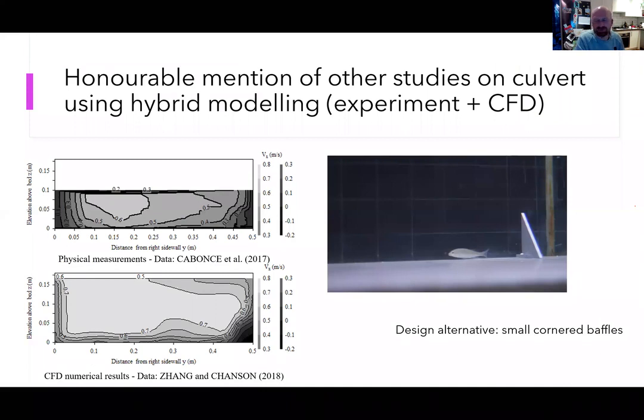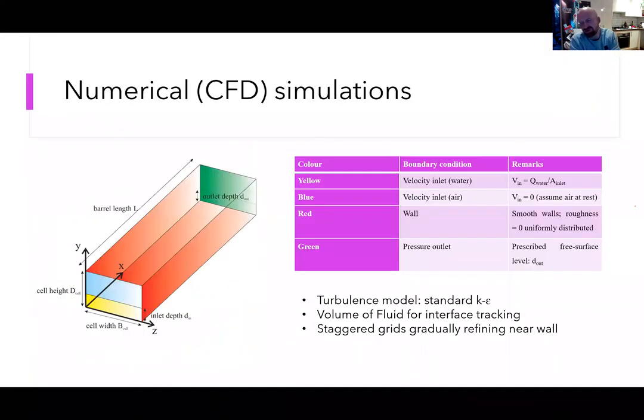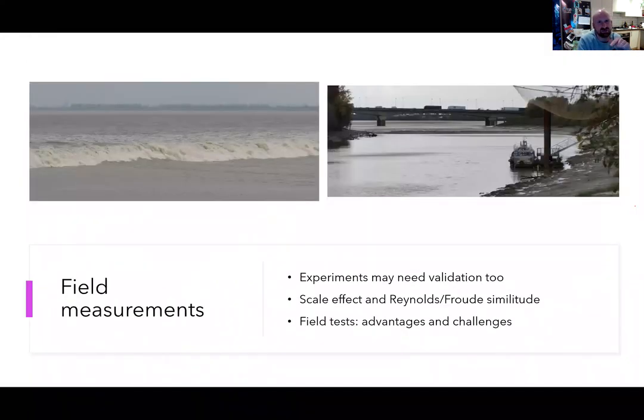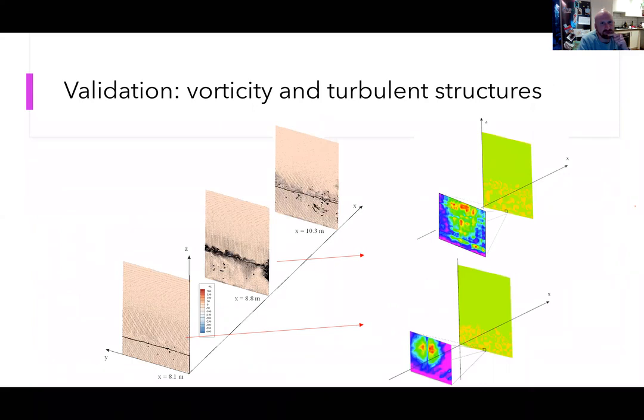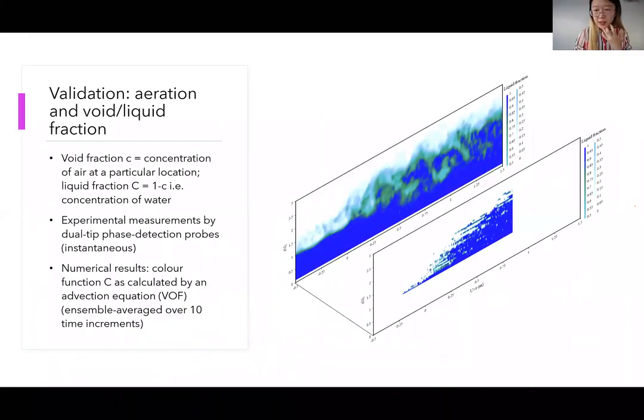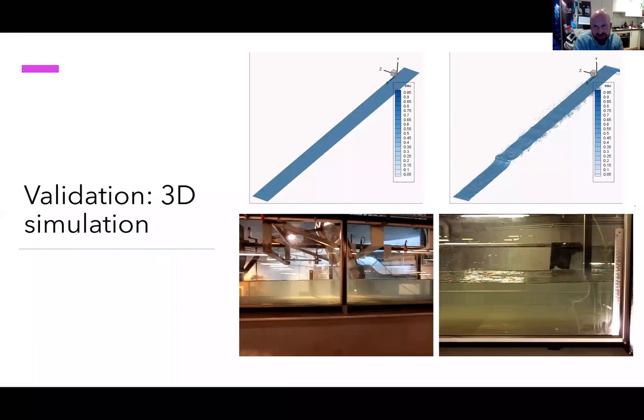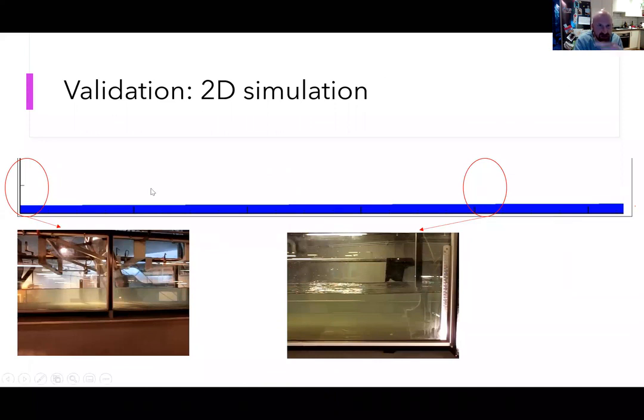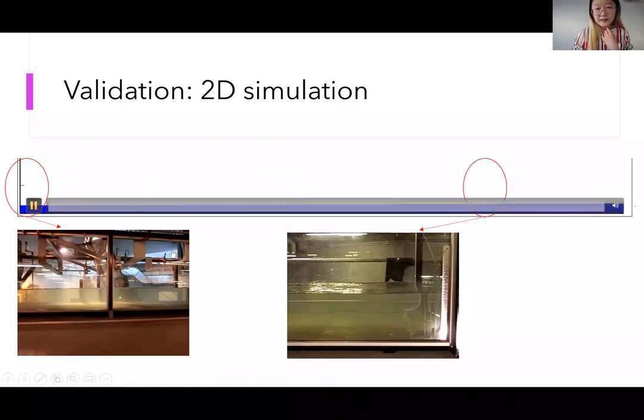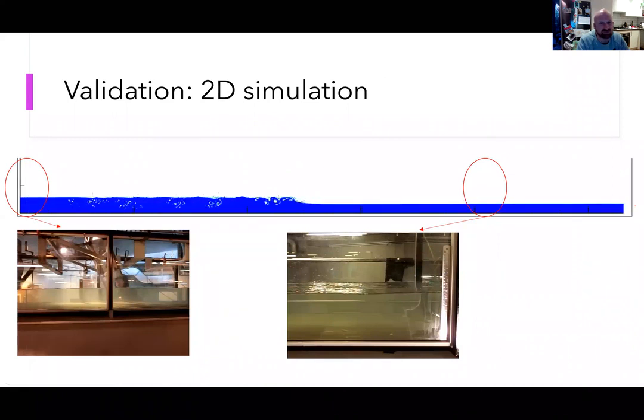While people are reflecting on your talk and thinking about questions, I just had a question. Where you have that aeration bias in the tidal bore simulations, is that a result of the non-monotonicity of mass fluxes at the free surface in that model? Sorry, can you go to the slide numbers? It was an earlier one, the 2D ones probably show it more clearly, where you had that aeration bias. Is that a result of a non-monotone flux scheme at the free surface?